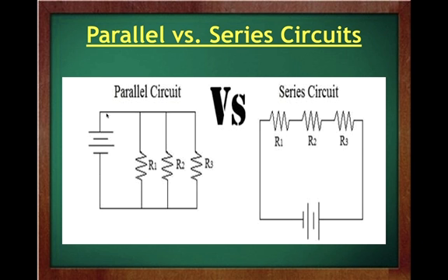And that's still saying that the current in, the current that was here before it split off into the different spots at this junction, is still going to equal the current out. So if this current splits into 3 different paths, by the time those 3 paths line up again, due to the conservation of charge, we get the same current back out here again, okay?